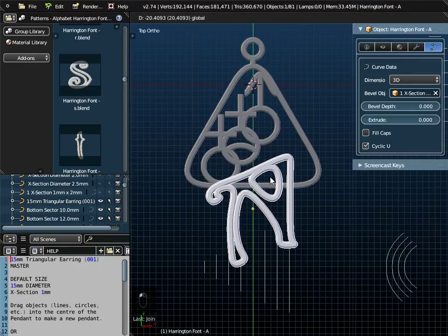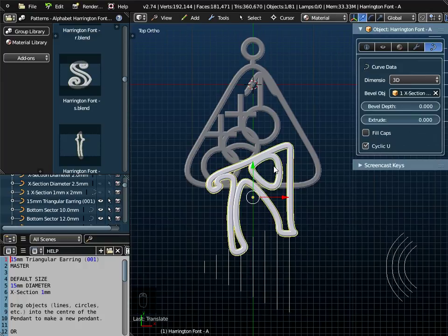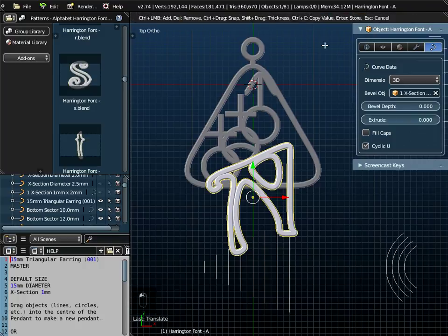And just drag that down and decide where you want to locate it. Now I'm going to put it there. I'm not going to go too far down, because you've got to take into account the length of this. If you want to see the length, you can use the ruler here, and I can measure from the top to the bottom, and so that's about 34-35 millimeters. So you don't want to go any lower than that really.